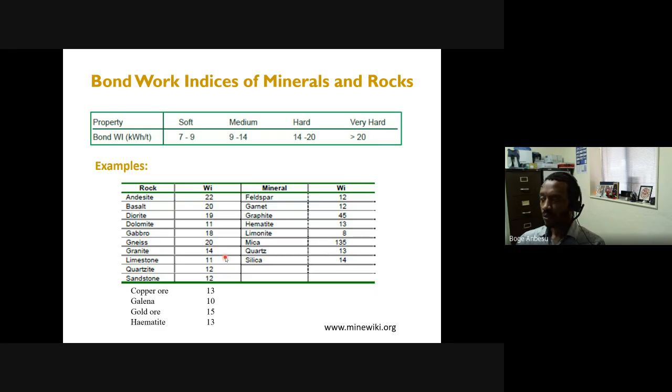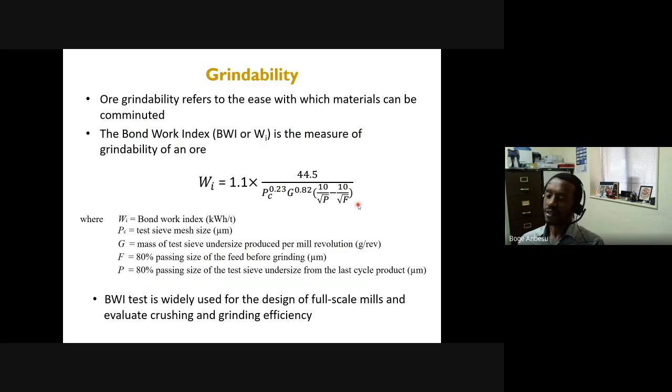finger, which means when you do grinding, it's very hard to grind a flat sample or flat particles, because they simply go through the balls, one ball hits another ball, and not much happens to the actual mica particles. So you don't grind them easily. And also when you screen them, because they're flat, they don't pass through the screen very easily. So that's why, based on this method, they give you a very high work index. In reality, they may not necessarily have high hardness, if you like.